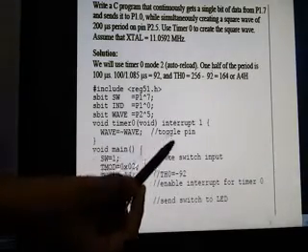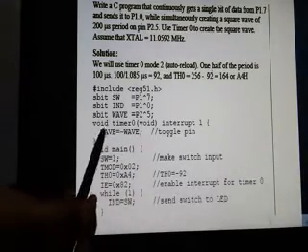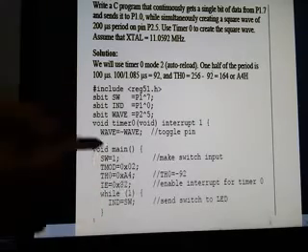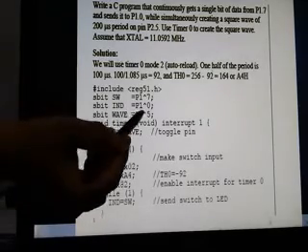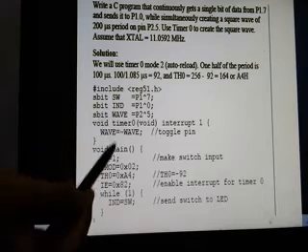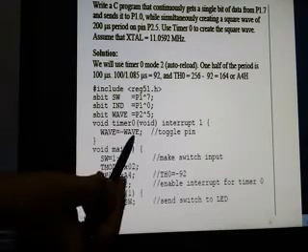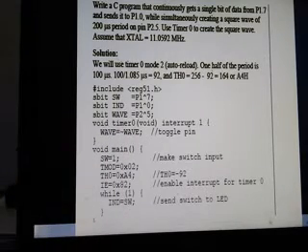Okay. What you have to do? Toggle the bit. So which bit? P2.5. This is assigned to a variable named wave. So wave is equal to complemented value of wave. x equal to complemented value of x we used to do. Now the name is given as wave. That's it. That is the name of the variable. You can choose any name, whatever you want.